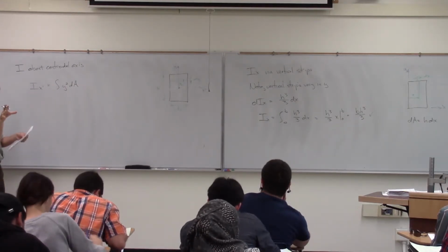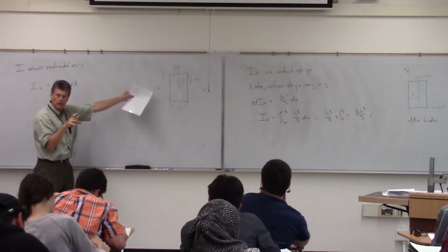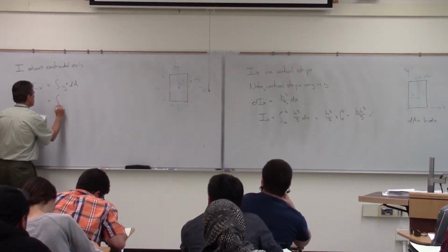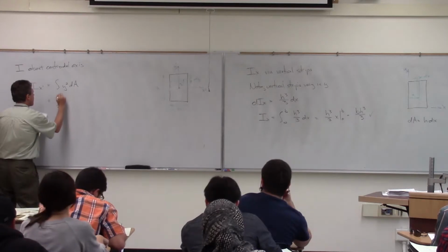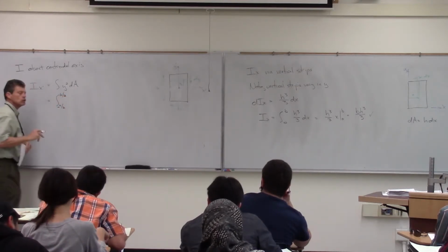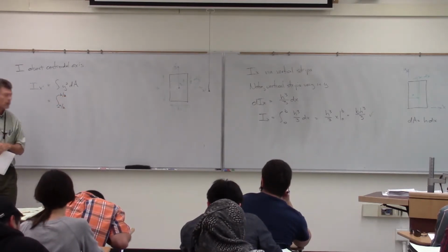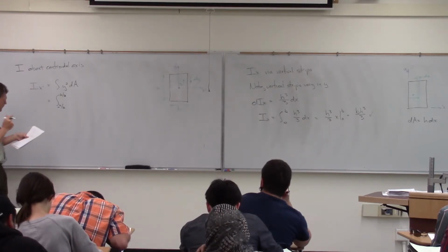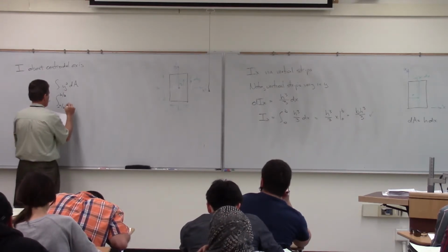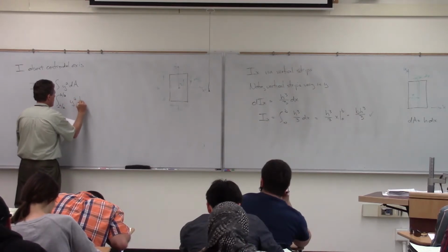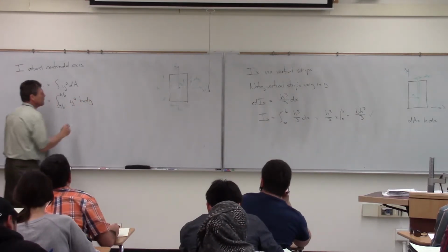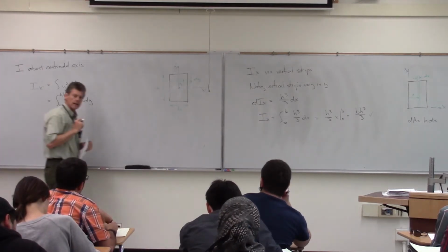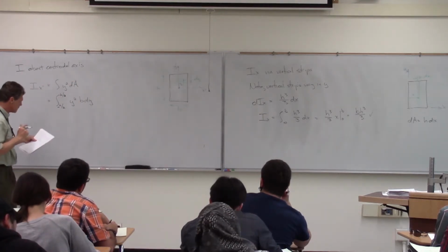Now this integration is going to be a little bit different because now I'm in the middle there. So my range of integration will now change from 0 to h, to from minus h over 2 to h over 2. Same section. And then noting my dA is simply going to be b times that dy section there.